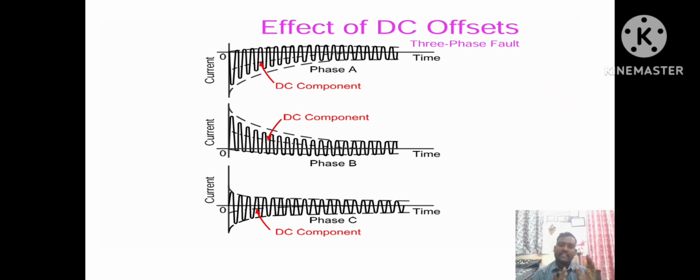So when the system is being designed, we should also consider the fault conditions. For the DC component, we use the square root of AC squared plus DC squared by 4. We can check the components of these two conditions, because your generator breaker or GCB should be capable of withstanding both components.